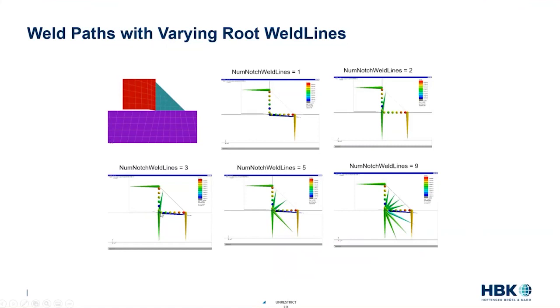There's also a path going upward from the root that's looking at peeling the weld off of the horizontal plate. The one before was peeling off the horizontal plate; this one's peeling off the vertical plate. And there's a third one going down through the vertical plate that's root cracking through the parent metal on that horizontal plate. We can go in and request additional paths, and what these allow us to do is start putting paths through the weld throat itself. So using the solid welds, we're able to analyze not only the classic failures we'd expect to see in the shells, toe or root failures, but we can also accurately calculate throat failures.